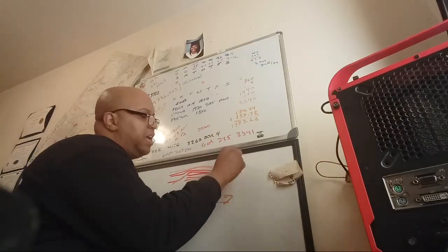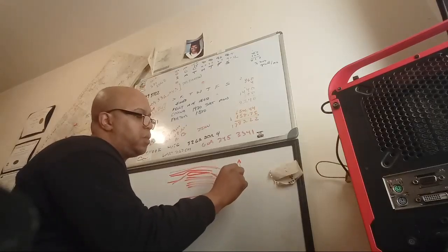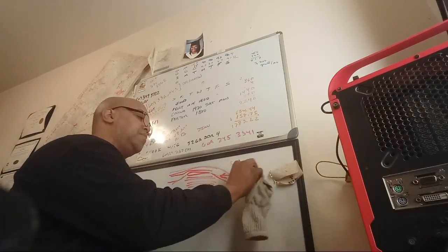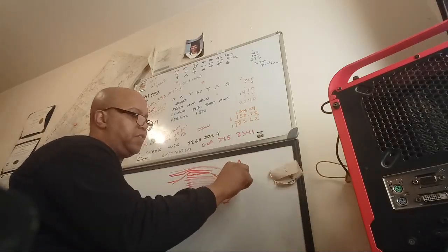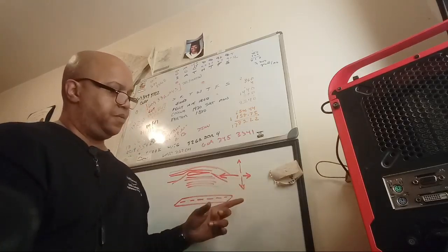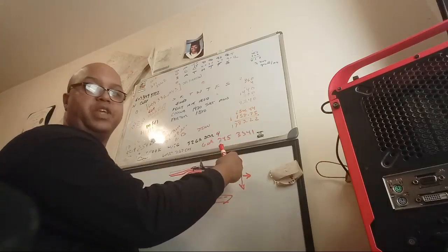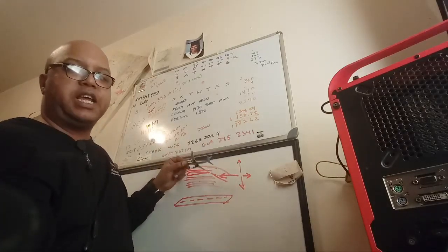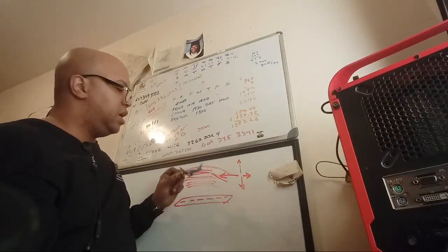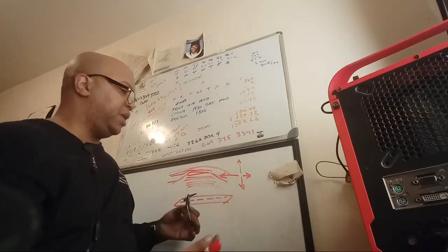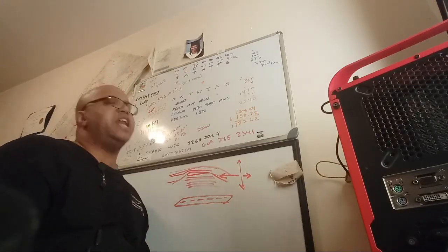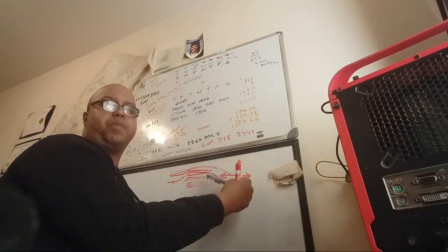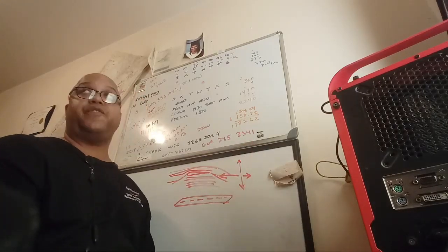So we're going to have our lift, our thrust, and our weight of the aircraft, but our drag is going to be minimized because of this disturbance. We're going to have the same amount of lift and thrust, and reduced drag when we're within one wingspan of the Earth. Up here at 2,000 feet, we don't have any issues. When we get within one wingspan of the runway, we can get some potential disturbances, aerodynamically speaking. On hot and humid days, you'll find that this is very pronounced. There are some days where you come in for a landing and the plane feels like it just does not want to land, especially if you come in too fast.